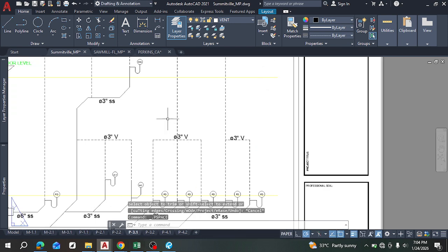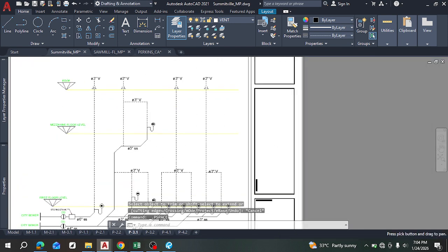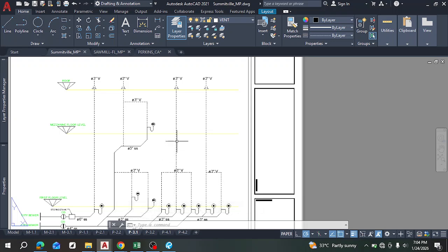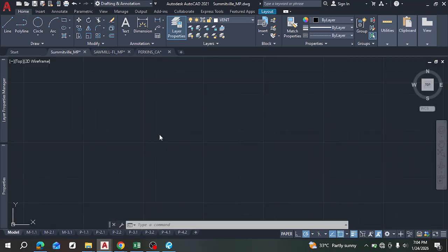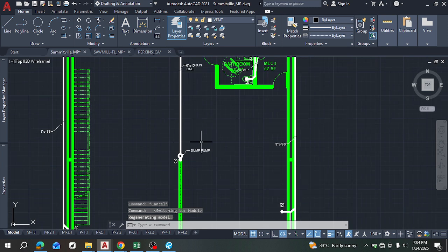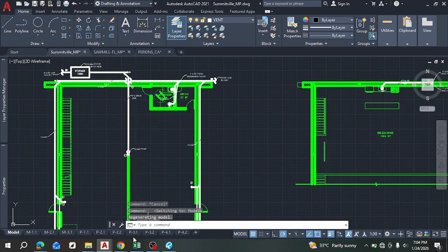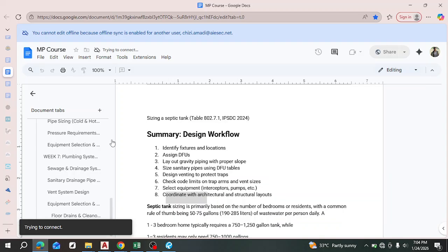So good there. Now if you notice the vent line, the vent penetration that passes here continues through this floor. This is all within the wall into the roof, right? Because there's no roof here and it's not advised. You can't vent it and then leave it hovering within the building, under the roof. So it has to go up into the roof before it is vented properly, right? So that is that. Are we missing anything?